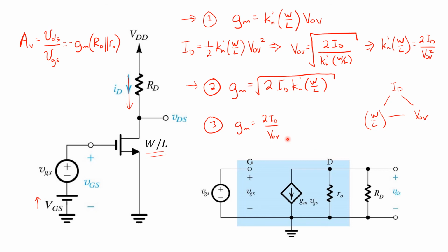In conclusion, the absolute best way to get comfortable with small signal analysis is to practice it. Remember the 3 steps. First, you find the operating point. Then you linearize the circuit around the operating point by finding the small signal parameters of the small signal model. And third, you analyze the linear small signal circuit.